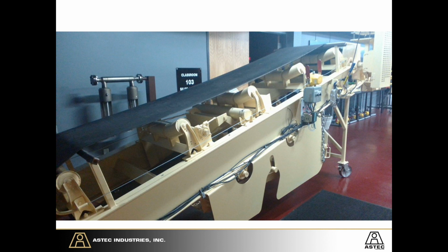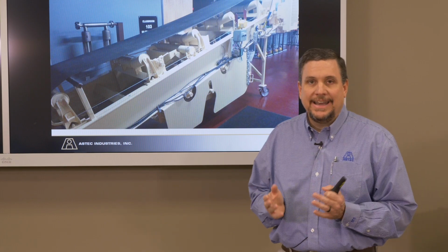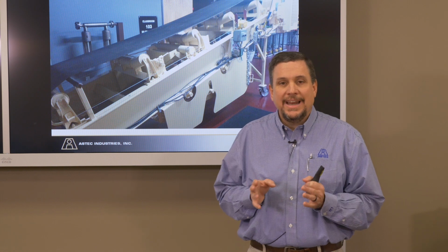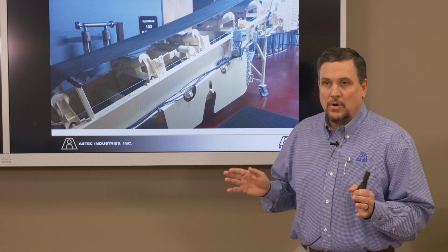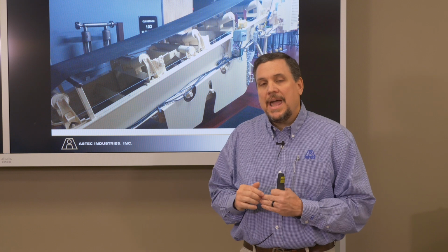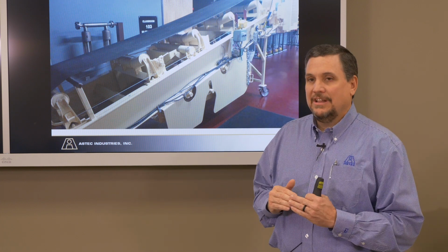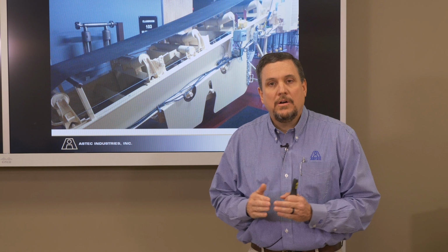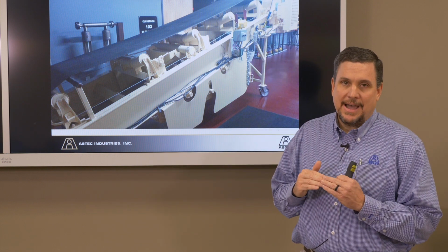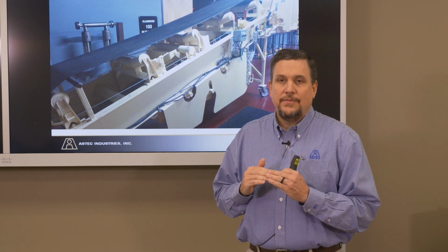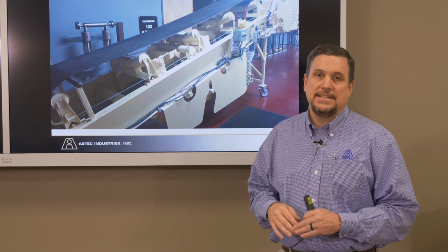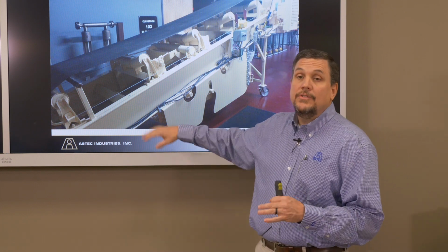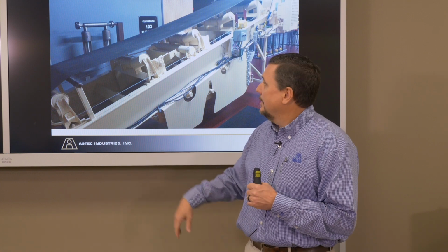When we talk about weighbridges and we talk about weighing, we want to look at the weighing idler, and we want to look at the 3 idlers above it and the 3 idlers below it. When we talk about string lining, that's what we're string lining. We're string lining all 7 of those rollers to be the same height. Some people will say, hey, I want that roller a little higher. No, I want that roller a little lower. You will never go wrong if you keep all of those idlers at the same height and you square them up to the conveyor. If you do that, you're basically just taking the inconsistencies out of the metal, which in turn will give you a quality mix, a very good weighing device.